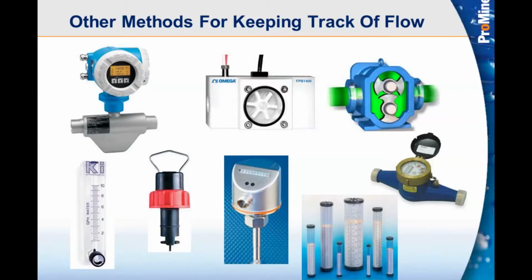It will display typically an instantaneous as well as a totalized flow. Instantaneous is the flow rate that we're pumping at as far as a volume over time, and then the totalized flow is how much flow we've pumped or how much volume we've pumped since we started that count.